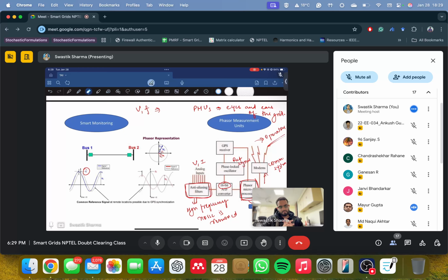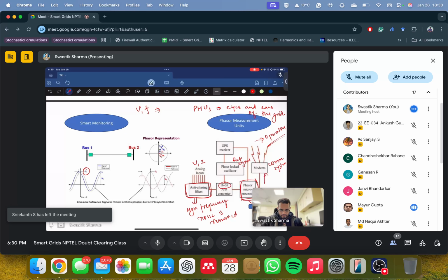There is a concept of grid security also, where you have a normal mode of operation, an emergency mode, or an abnormal mode of operation. I read an IEEE paper on whether PMU implementation can be used for transitioning between the states, or for indicating to a distribution owner, or people like us operating a very large industrial network, that the grid is moving towards instability.